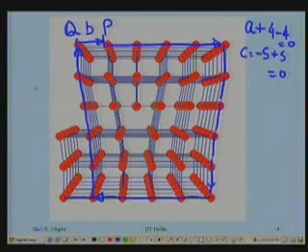However, this is what I did to the top part, displaced it to the right by 1 interplanar spacing. If my friend decides that he does not want to go clockwise, he would like to go anti-clockwise, he starts at Q, goes along, makes the net displacement 0 and reaches point P. Now to close the circuit, he will have to add P to Q, not Q to P. Magnitude is alright, but the direction has changed.